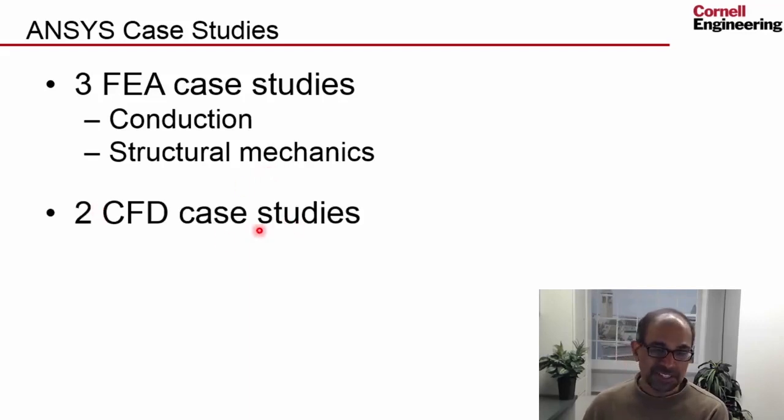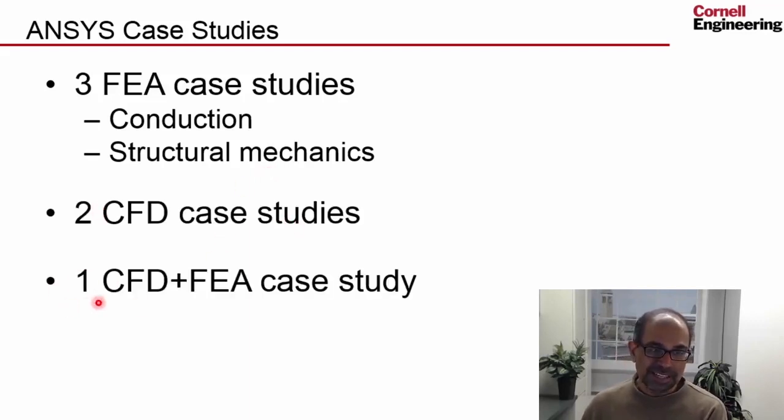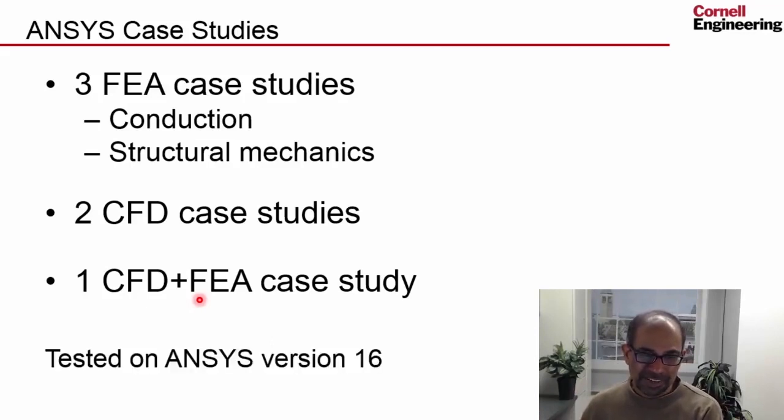We'll do 2 CFD case studies, and we'll do 1 case study that involves CFD and FEA, the coupling of the two. This will show you one-way fluid structure interaction. So in this coupling, you'll transfer the loads from the CFD to do a structural analysis with FEA.